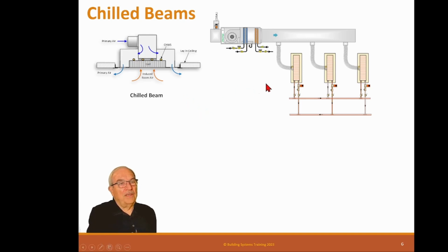So some bright individual said, well, let's just put a cooling coil up here, because that gives us a whole bunch of area. So instead of doing all the ceiling tiles, we can just do some, and we'll take that displacement ventilation system and put it across these grills. Then, of course, it's no longer a displacement ventilation system, it's a regular ventilation system.